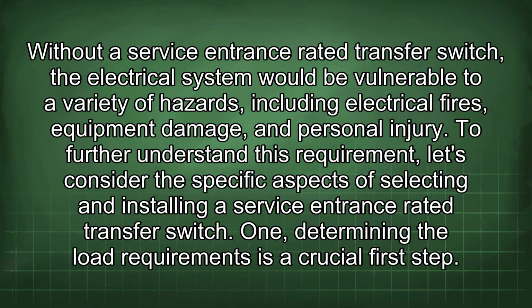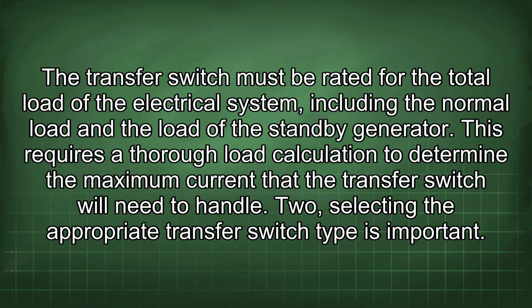Without a service entrance rated transfer switch, the electrical system would be vulnerable to a variety of hazards, including electrical fires, equipment damage, and personal injury. To further understand this requirement, let's consider the specific aspects of selecting and installing a service entrance rated transfer switch. 1. Determining the load requirements is a crucial first step. The transfer switch must be rated for the total load of the electrical system, including the normal load and the load of the standby generator. This requires a thorough load calculation to determine the maximum current that the transfer switch will need to handle.